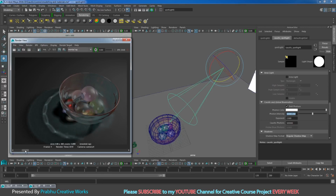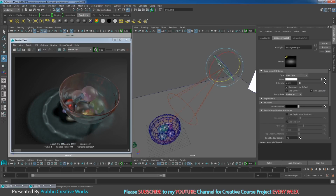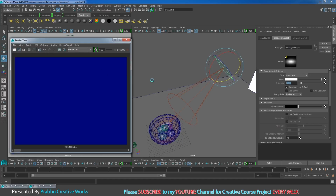Okay, so this is what we need over here. But I want a little bit more scene intensity. So I will select my area light and give intensity to 1. Keep this image for comparison and click render.